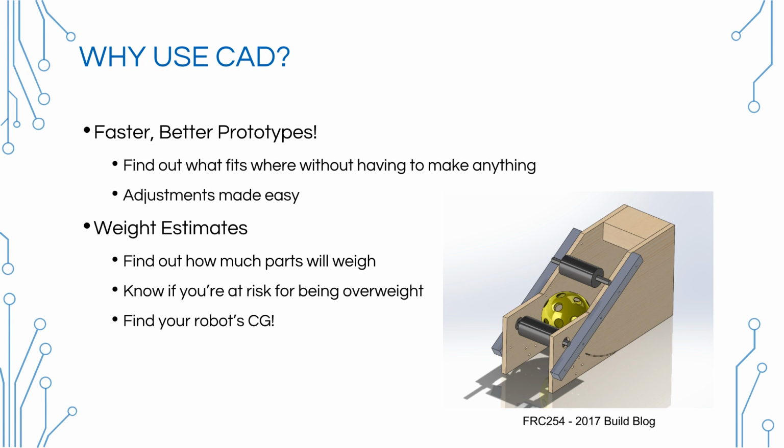And one of the teams that does this really, really well is 254. And I mean, they do pretty much everything very, very well. They have a laser cutter, so they CAD all of their prototypes and cut it out of like 1/4 inch or 1/2 inch thick plywood, and that allows them to make very, very fast changes in their prototypes, but also they can build in the adjustment that they needed to try and find that sweet spot.